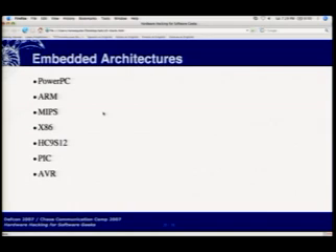If anybody caught Bunny's talk at ShmooCon 2 years ago, he basically decapped a chip, removed the plastic from the top of it, and then shone UV in at an angle to get under the aluminum layer that was covering the fuses that were set when the chip was set to be write only, and that way managed to clear the fuse and dump all the code out of the chip. Needless to say, that's not a very easy operation. It's doable, though, but not something a noob should attempt. Yeah, he used a lot of acid for that to etch the chip top off.